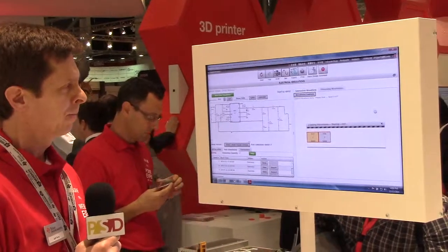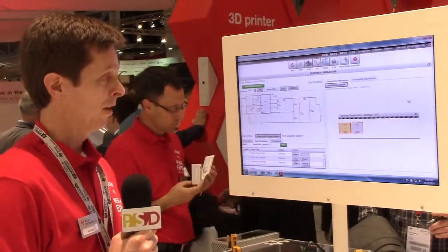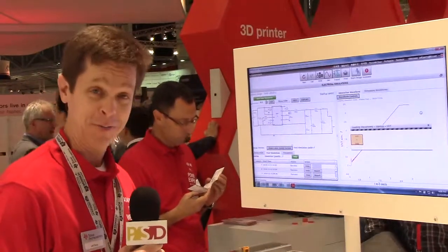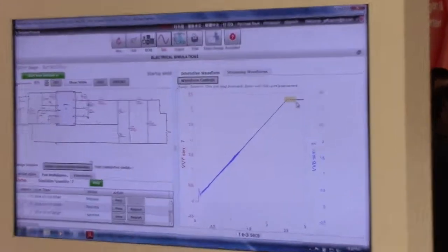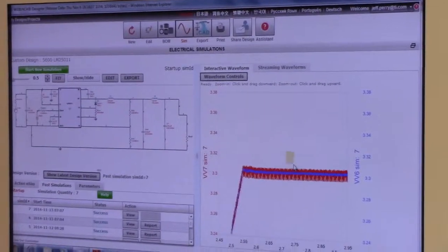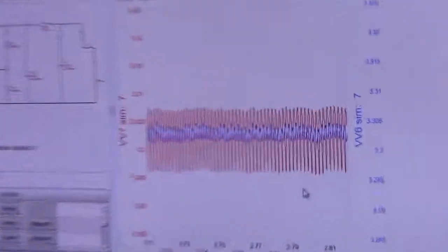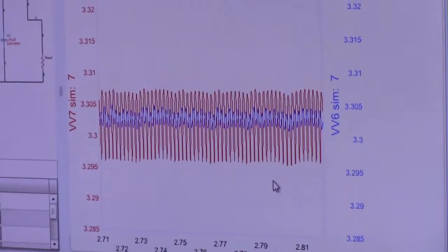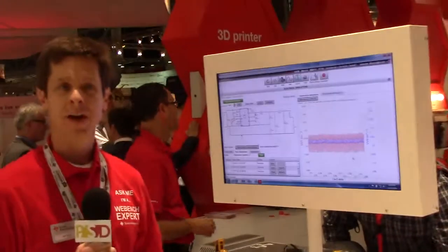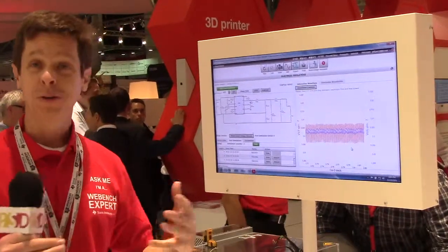All right. Sometimes it takes the waveforms a little bit longer to load because we are operating in an Electronica internet environment here. Okay, so our first waveform loaded, that's the one before the filter. So let me go ahead and just zoom in here. All right, so you can see the red one is before the filter. That was the output of the original power supply design. The blue one is after the filter here, and you can see the attenuation that we got from adding that circuitry to our design. So that concludes our little mini tour here.